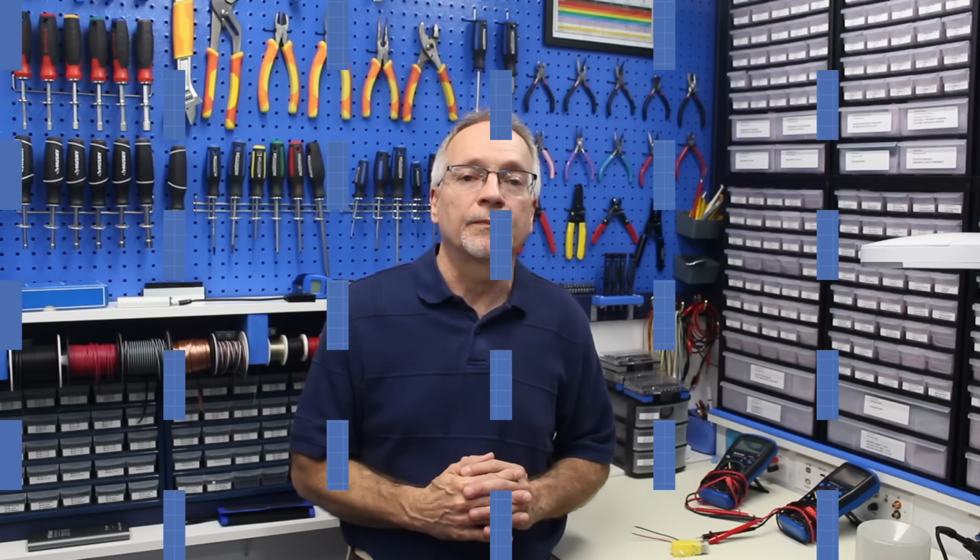Now this is a conventional LED strip light as opposed to the programmable or addressable ones, and so we basically have a red, green, and blue line, and they require 12 volts on each to drive the LEDs, and a fair amount of current because this is a 5-meter long strip light. And so we're going to use the MOSFETs to drive each of the sections. We're also going to add a few potentiometers onto our circuit so we can control the brightness of the red, green, and blue. So let's go and take a look at that right now.